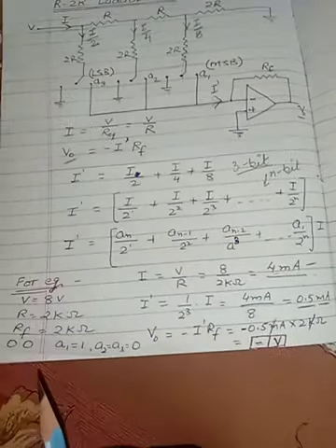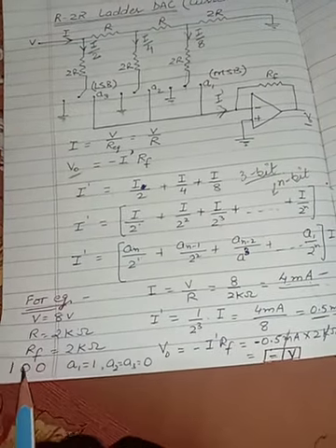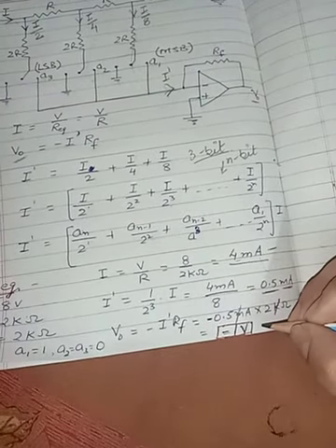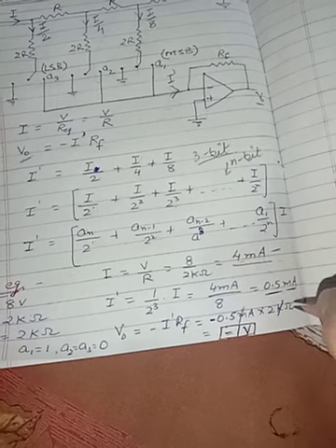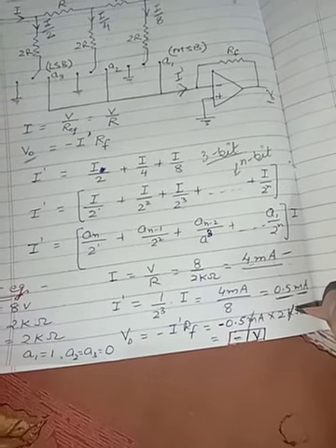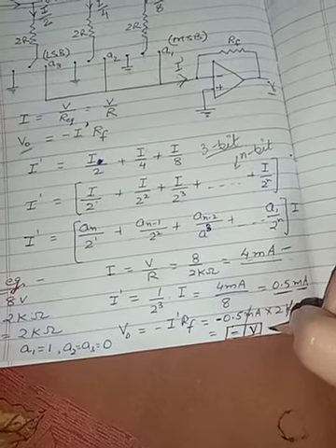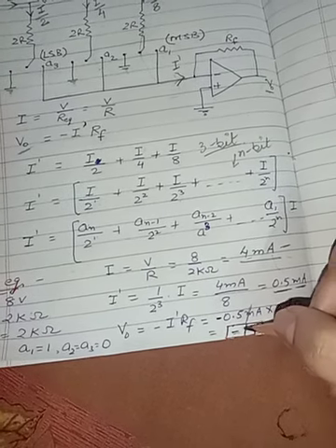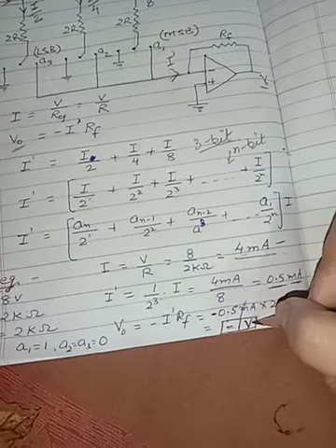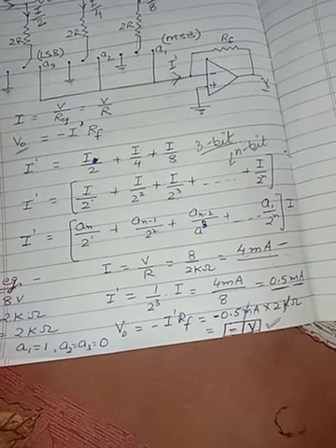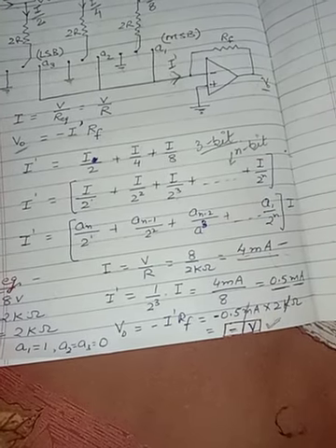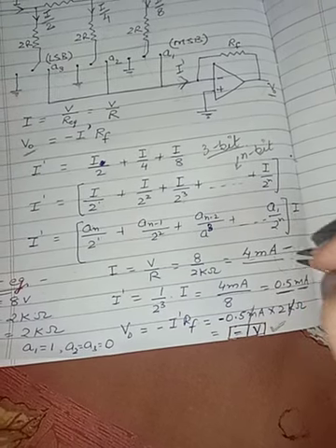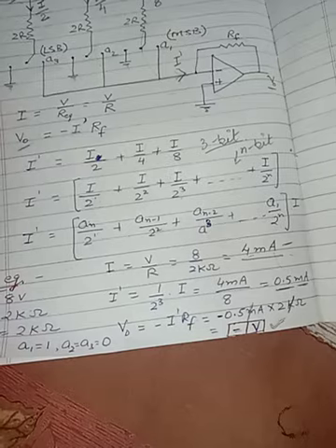So that means when we provide the 100 digital input, the analog output voltage will be 1 volt. If someone is asking for the magnitude of the output voltage, then you will tell it as 1 volt. If they are asking for the sign also, then you will take it as minus 1 volt. Otherwise this is a 1 volt magnitude voltage.